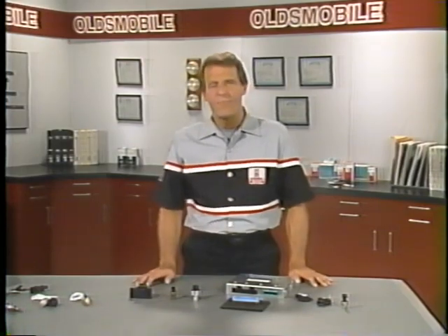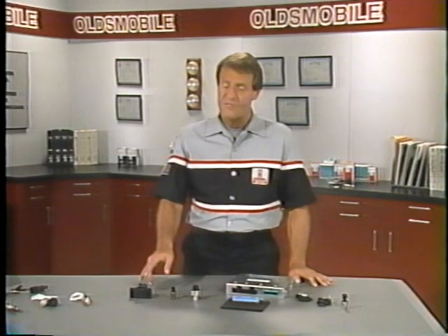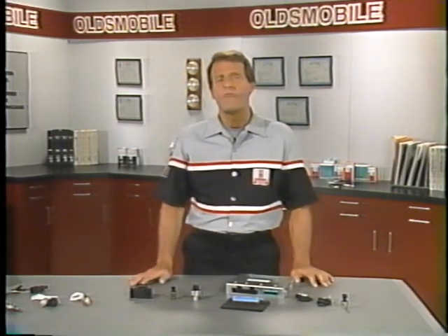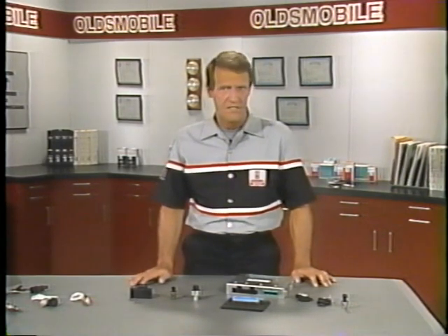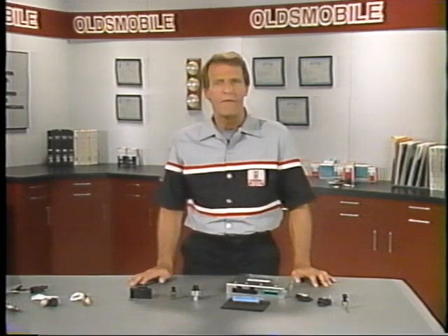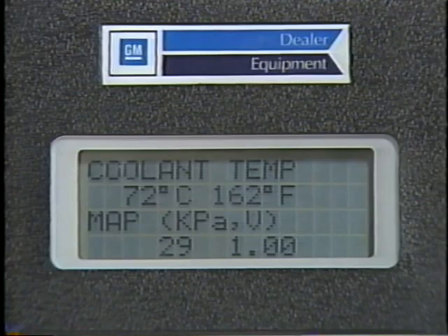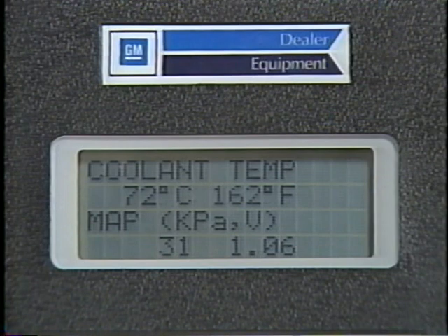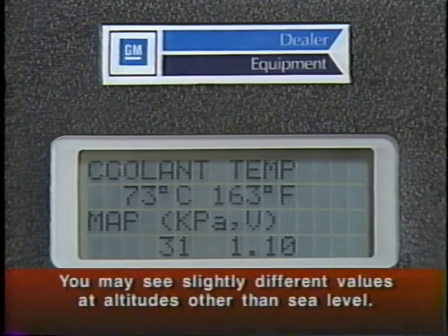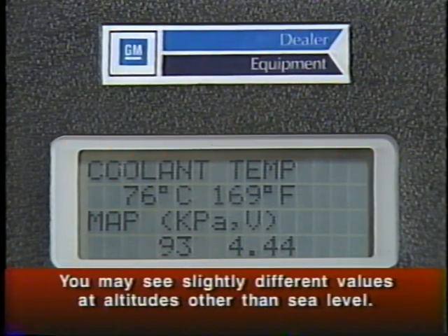For EFI and PFI systems, MAP sensor output voltage should be about 4.8 volts with the vehicle at sea level, ignition on, and the engine not running. With the engine running, the signal voltage ranges from 1 to 1.5 volts at idle to 4 to 4.5 volts at wide open throttle. The PCM monitors these signal voltages many times per second.